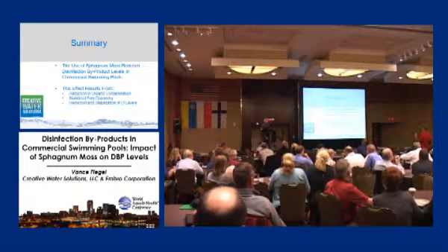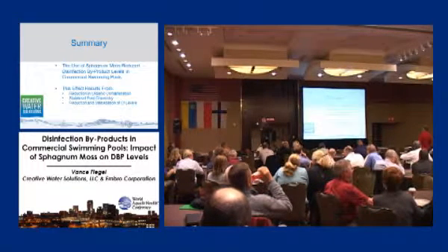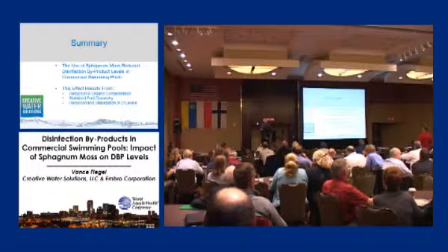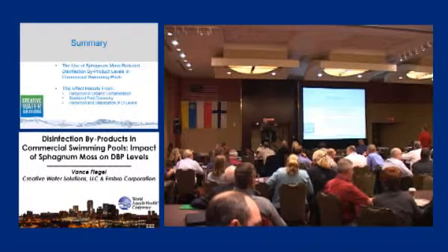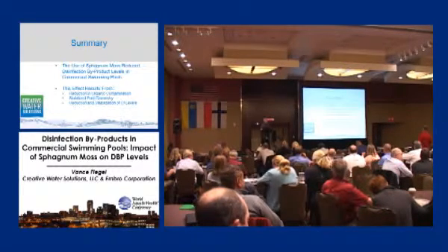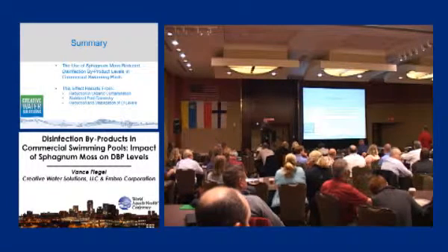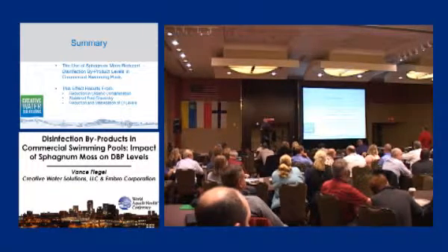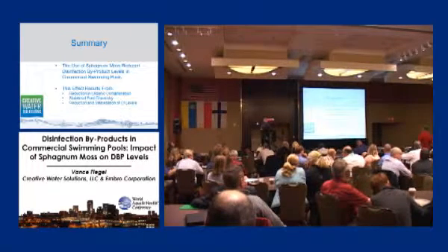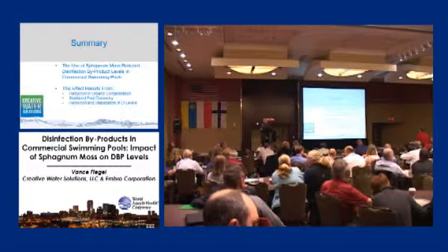Okay, so if we also drop the chlorine values in the pools, isn't that automatically going to drop the chloramine values as well as the disinfection byproducts? Yep, absolutely, it should. That's part of the reason we may be seeing the decrease in disinfection byproducts, because there's less chlorine in the system and there's less chlorine demand, so there's less chlorine being pulled out of the system. So can you differentiate then between? Not right now. We're in the process of trying to do that, but we haven't been able to differentiate that right now. Okay. Thank you.